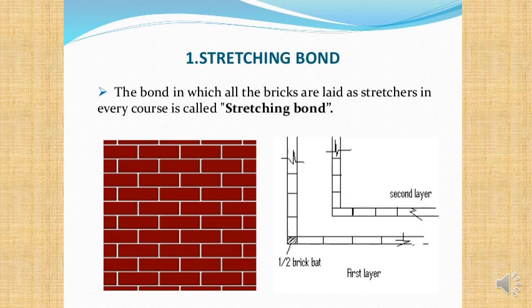If you just had blocks perfectly on top of one another, then it's going to be a considerably weaker wall, because the crack that would need to form in the wall would be a much shorter distance, and so far less energy will need to be exerted on the wall to break it. So that's called a stretcher bond, or a stretching bond is another term. I don't care if you use the subject or the verbing noun form, stretching or stretcher bond. They are exactly the same.